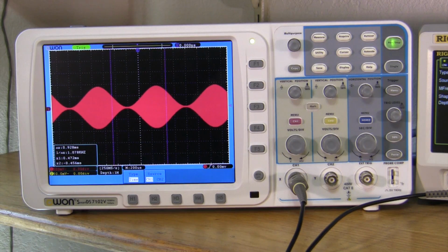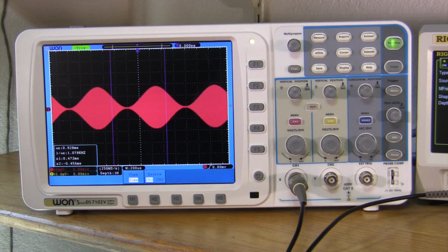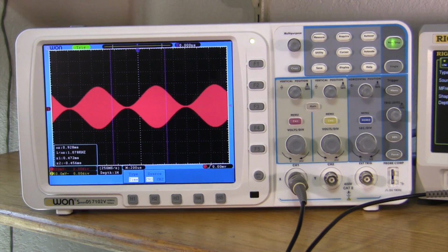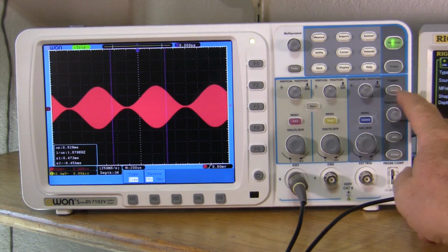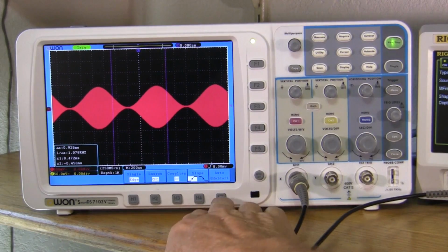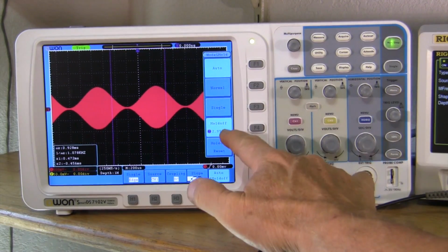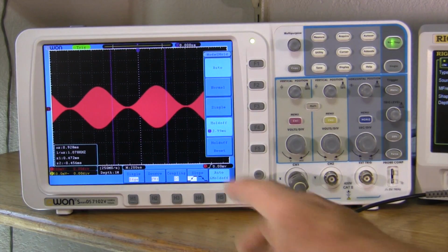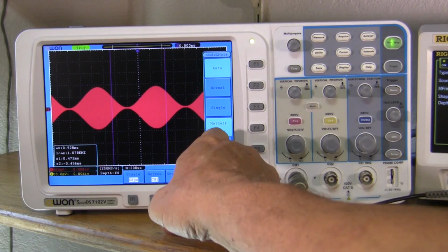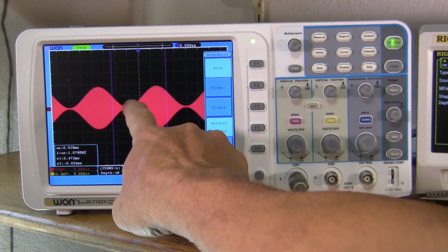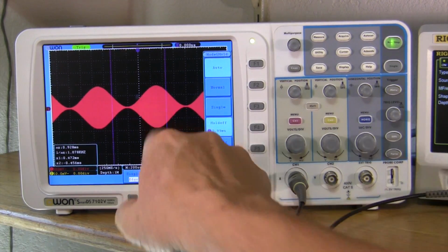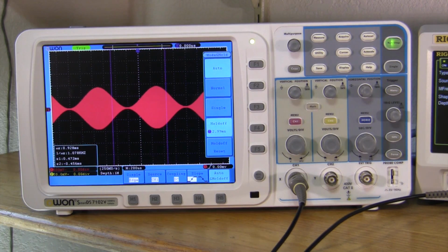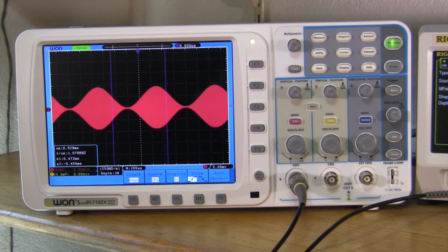The last time I did this, that was creeping through and I had to hit stop to look at that waveform. But what I discovered and had forgotten, because I had not been using this type of scope for a while, is that, especially on a digital scope, you've got to hit your trigger and then hit your hold off. I put it on auto and I just adjusted this. It'll grab the RF frequencies unless you use the hold off to make it look there and then there. So it might trigger here and it might trigger there, as opposed to triggering there and on the next cycle or something. And that's why it's stable now. So it's worked out pretty well.